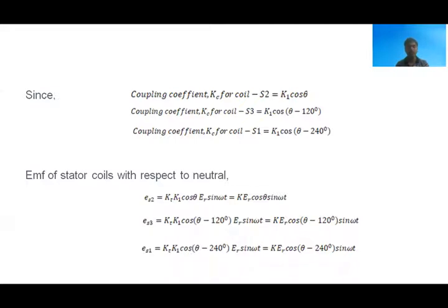Similarly, the EMF induced in the stator winding S3 is equal to Kt K1 cos (theta minus 120 degrees) ER sin omega t, that is equal to K ER cos (theta minus 120 degrees) sin omega t. In a similar way, ES1 is equal to Kt K1 cos (theta minus 240 degrees) ER sin omega t, that is equal to K ER cos (theta minus 240 degrees) sin omega t.